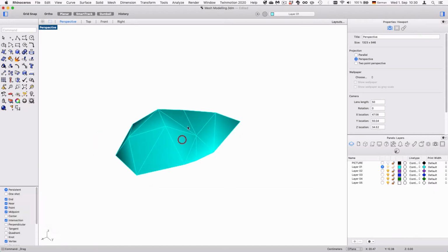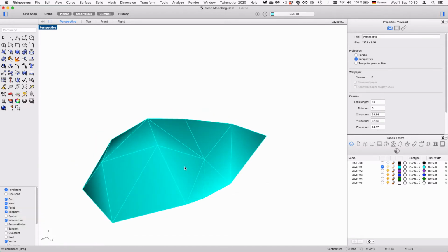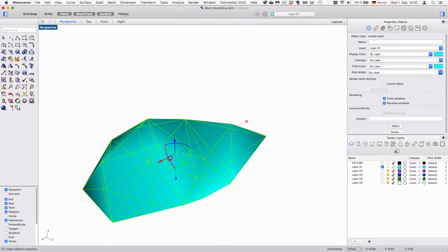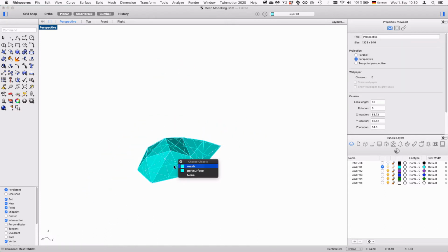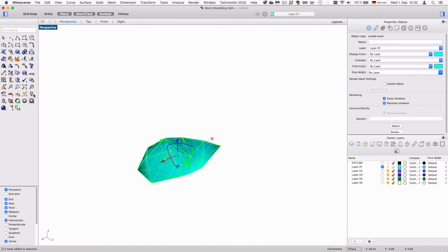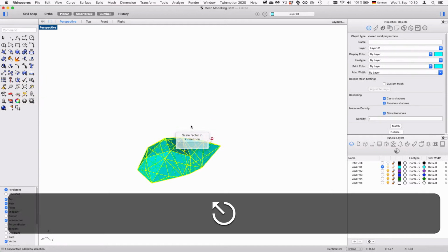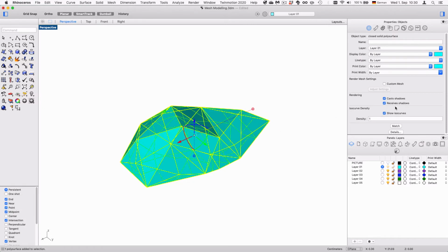And then let's see how to generate an unrolled surface pattern from that. What you want to do is create a NURB surface, a poly surface. If you press OK, you see there were these lines added, and now if you click here, you see there's a poly surface and a mesh. Let's hide the mesh for now. If you click here on the light bulb, you see there are all these extra lines, which are actually the ISO curves.